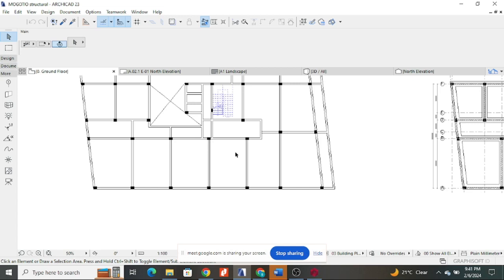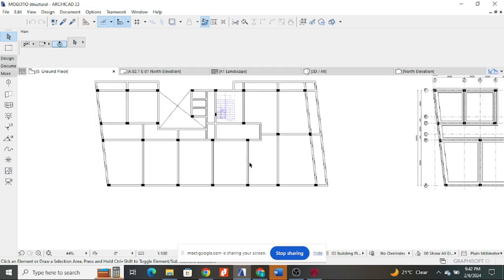Yes, that is what I was saying. After you have gotten those beams, you still superimpose the floor above to find out whether it has any walls that are very heavy or any big spans that might require additional beams. Those are the ones that now can run inside the rooms, and maybe cantilevers if it is allowed.